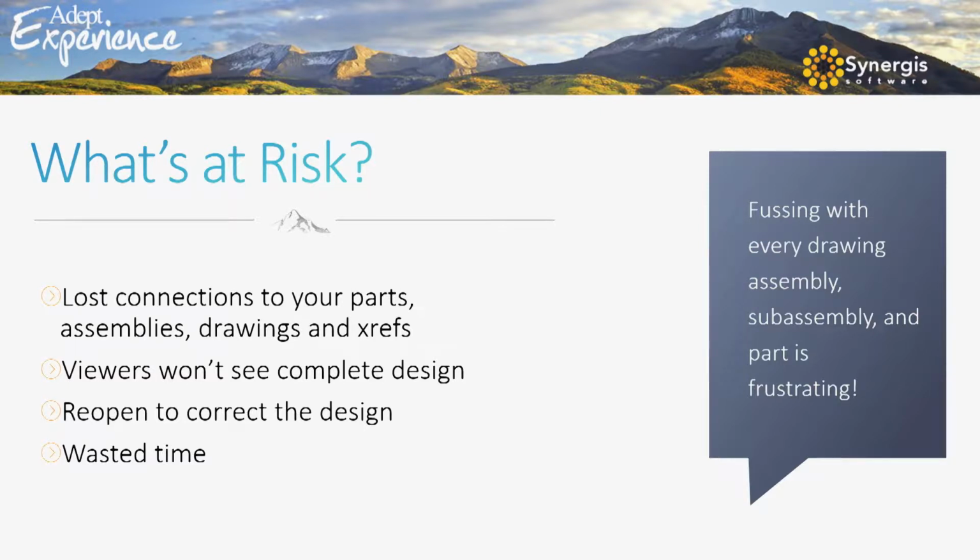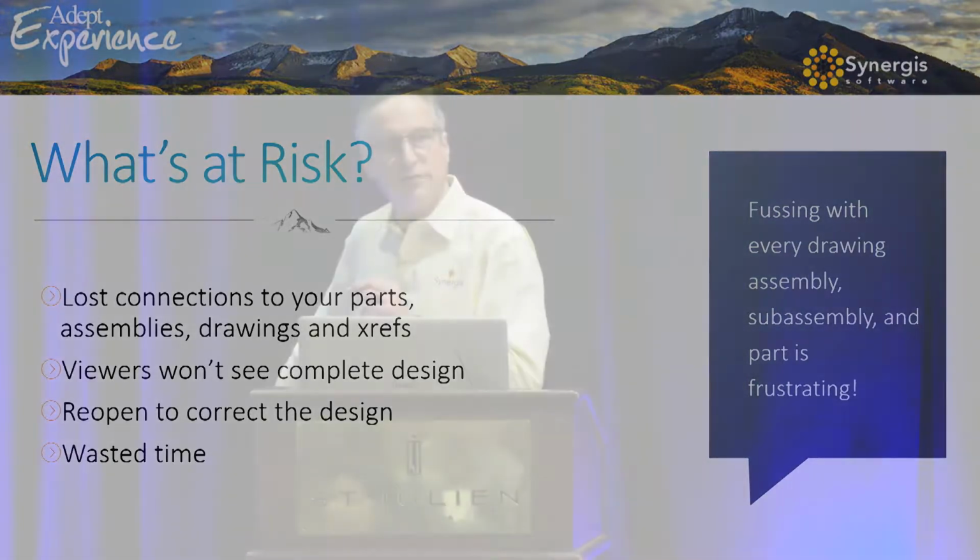And I've actually had two people come up and talk with me today, well, one yesterday and one today, about the dangers of not using it. And one of the big ones is losing connection to your designs. Whether they're X references or whether they're parts and assemblies and sub-assemblies and drawings, it's very, very easy for somebody that's not using a task pane to go and create things that are pointing to a drawing over here on my D drive, and I've got a couple parts stored over here on my C drive, and on the J drive is where I keep all my special parts. That is going to be a recipe for disaster long term.